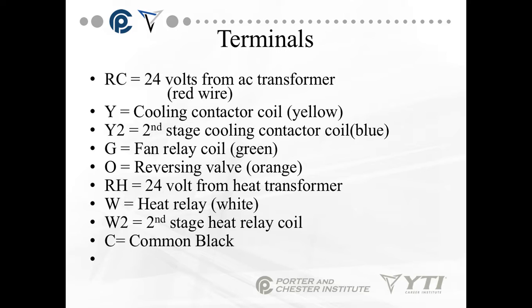Normally those two are jumped together. W is your heating relay. W2 is your second stage heating relay. And C is a common or black. The C terminal, the W2, the Y2, and the O you will not see on every thermostat.